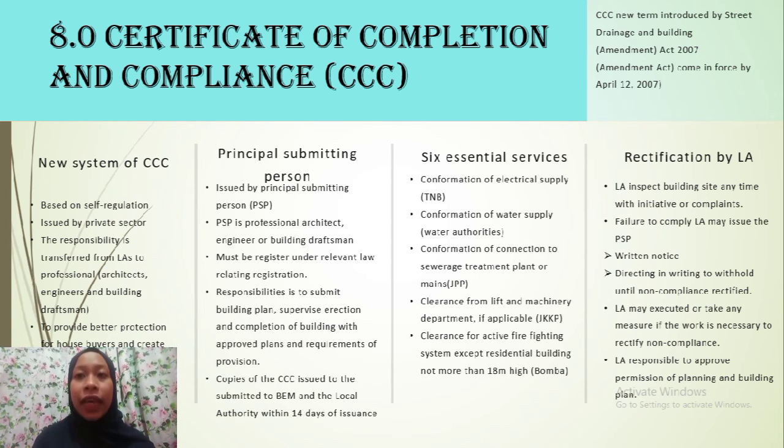The PSP responsibilities include submitting building plans for approval by the LA and supervising the erection and completion of the building in conformity with the approved plan and the requirements of the provisions of the act or by-law, ensuring all the technical conditions imposed by the LA have been duly complied with, and ensuring that the building is safe and fit for occupation.